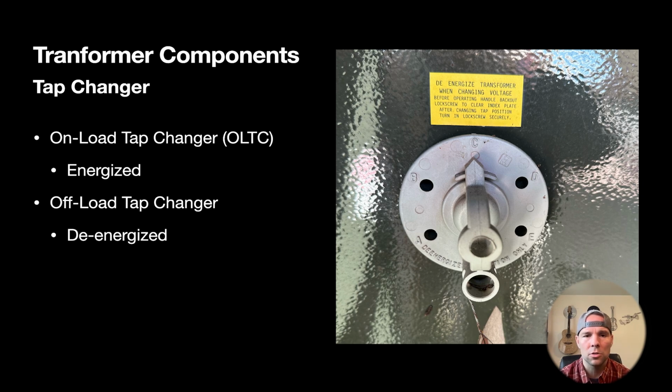Power transformers that step up the voltage just outside the power plant generation facility can auto tap change, right? They have an auto changer that can do it under load automatically. The reason is that to de-energize such a key transformer right after the power generation, you would have to shut down a very large portion of the grid to make adjustments.